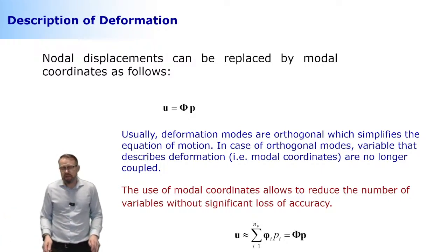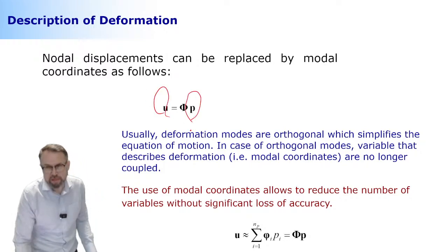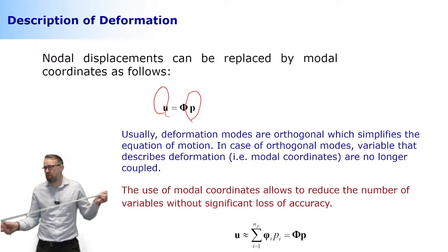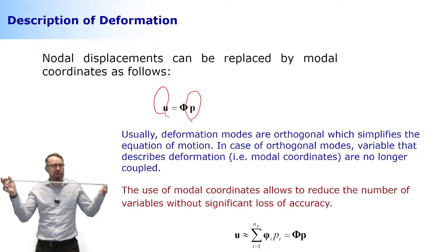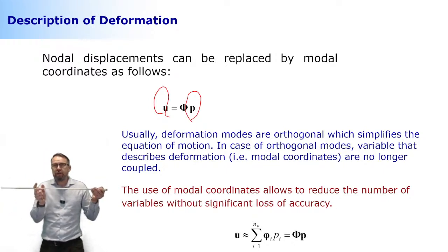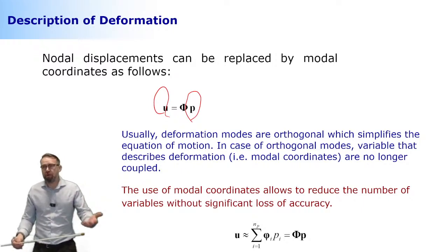We're going to do this by moving from nodal space to modal space. What relates these two spaces is the assumed deformation mode. This time we look at how the entire structure behaves, no longer a single element. We look at the possibilities of how the entire structure can deform. Each of these ways that the structure can deform will be our new unknowns, called modal coordinates.